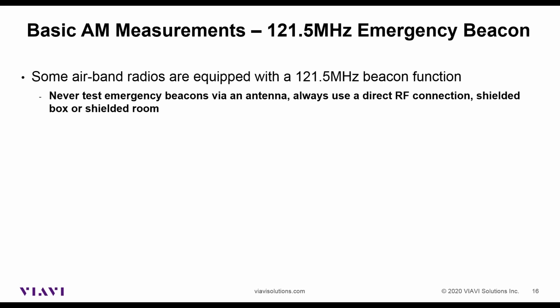I've seen emergency beacons in a screened box, especially on the 406 megahertz satellite channel. I've seen those cause an alert and helicopters get scrambled, and the radio was already in a screened box. So again, be very careful when you're playing with emergency beacons. I say the same thing if you press the red button on a digital radio these days. If it's a live network and you're trying to test the radio on a live channel, be careful with those emergency buttons.